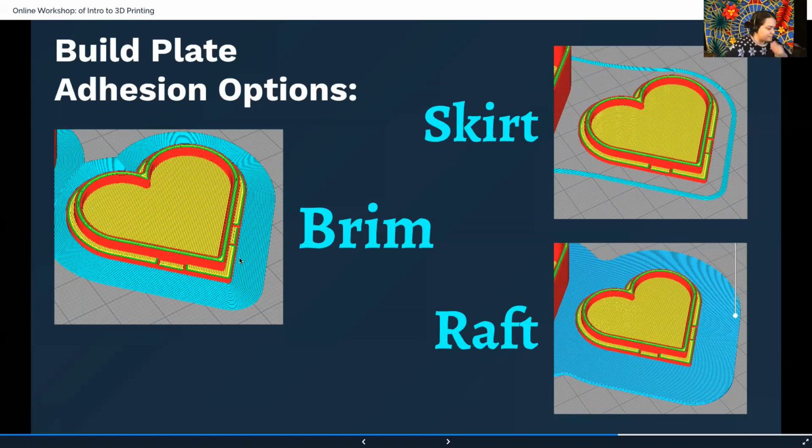And then this is good for this next one. The brim is good for if you're going to have a tall piece. I recommend doing a brim. It just prints a really thin layer, several lines around it to kind of anchor it to the bed. So if you've got a tall piece, it keeps it from wobbling or falling off, which would be really bad.